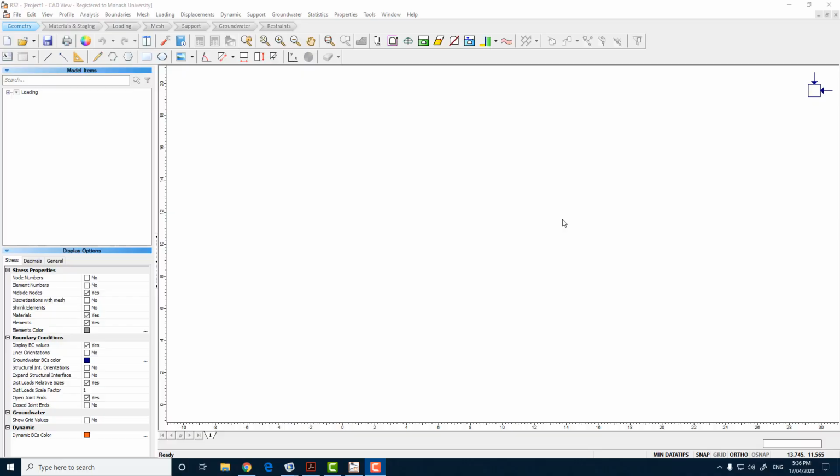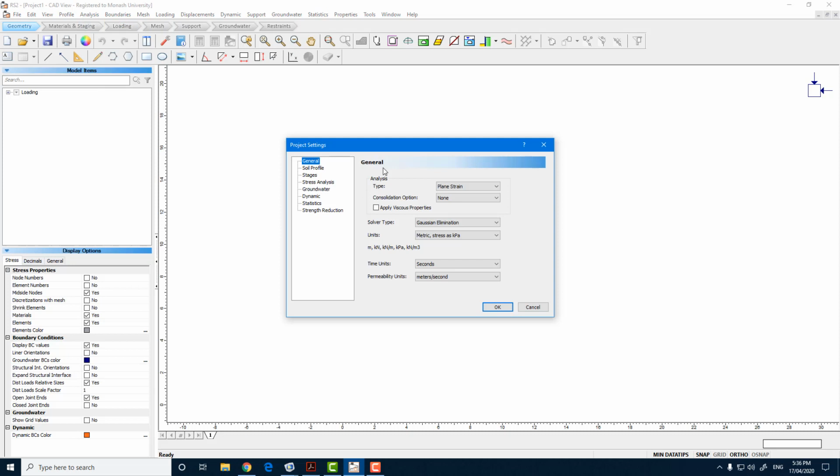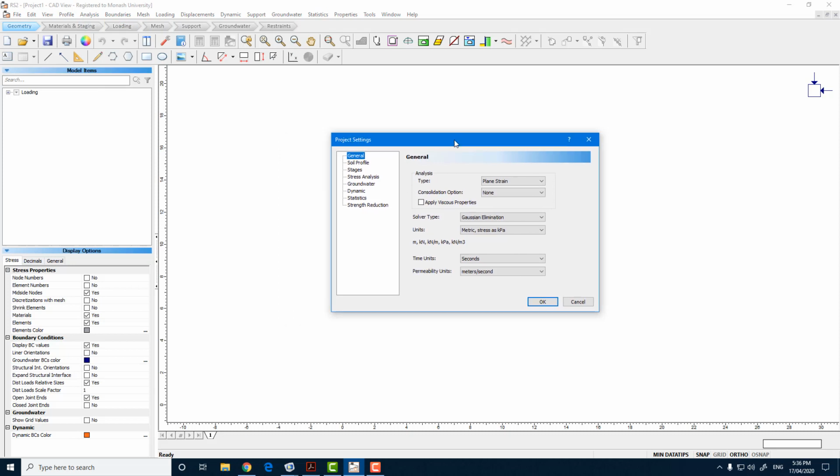Hello everyone. In this assignment support video, we will look at the main steps involved in the creation of the numerical model for your assignment and also some aspects of the result analysis. So we start with the RS2 software open and we go to analysis, project settings, where we define our important project settings. So initially we make sure that our units are in kilopascal, kPa.